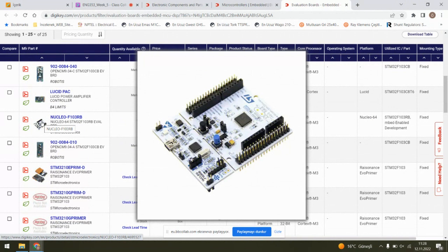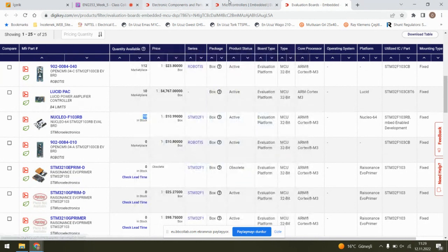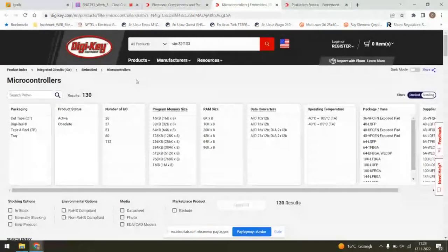But do you know, Arduino is basic. It's for rapid prototyping. Arduino is good, no problem. But for advanced, high control applications, for example in Arduino, the clock frequency is very low. In this microcontroller, the clock frequency is upper than 80 megahertz. Generally, in motor control applications, we recommend a minimum 72 megahertz clock frequency. Okay. Now we can check our microcontroller.